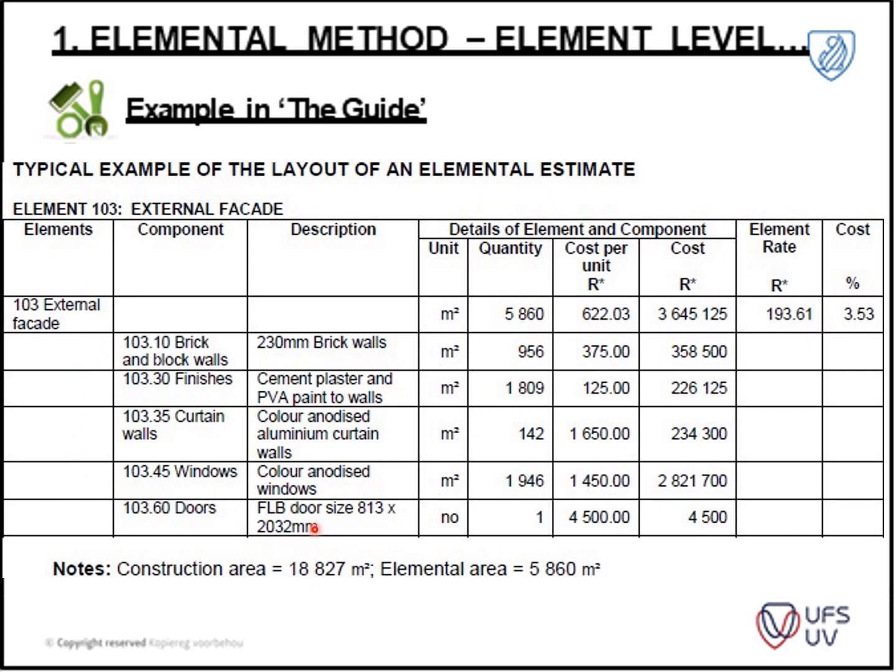Something that you should also take note of is that this section is basically the elemental guide that it's contained in, and then you've got your quantities and your description, your components, which is then described, and then you can have multiple items underneath, for instance brick and block work. So for instance, if you've got a 250 wall, or if you've got a 350 wall, you need to divide it in between here.